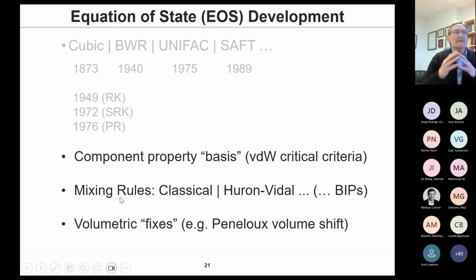For the cubic equations, both SRK and Peng-Robinson, the accuracy of calculating petroleum mixture liquid densities with the constants A and B is only around plus or minus 5 to 15, 20% accurate. It's not really accurate enough for important engineering calculations where gravity has a major role.